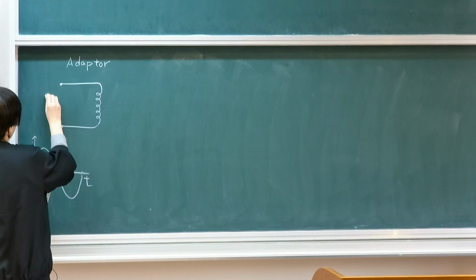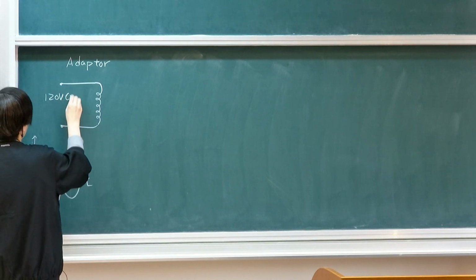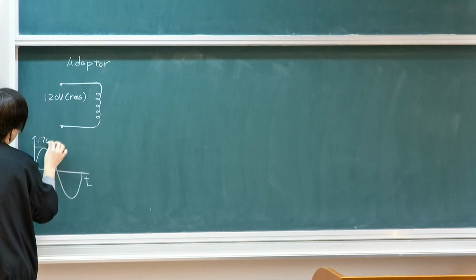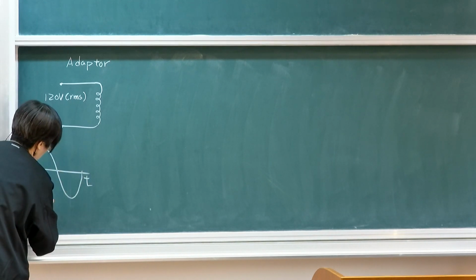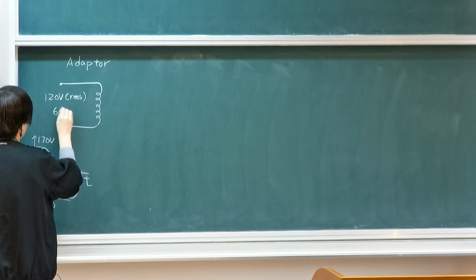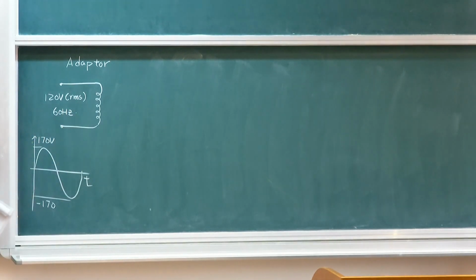It's typically 120 volt, that's root mean square. That corresponds to a peak level of 170 volt sine wave at 60 hertz. So there are 2 key components: how fast does the signal change? That would determine the cycle of your rectifying need. And of course, the other thing is the peak level. Once you know this is your input signal, that's your input power.